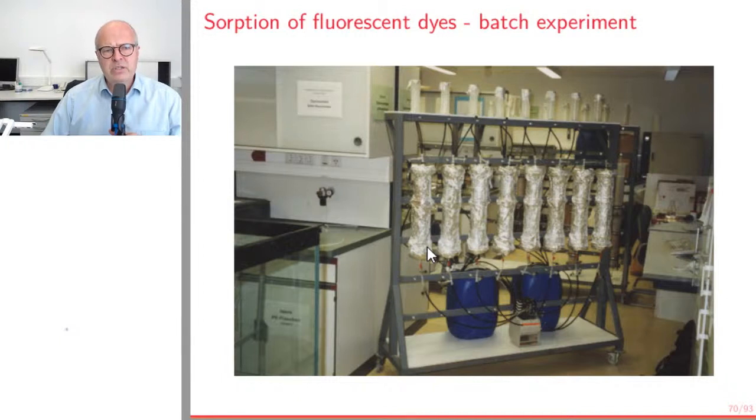If you do research and you want to work on the estimation of velocities and really try to avoid any bias, and you need to justify and thoroughly prove what you do, it's wise to do parallel column experiments in your laboratory and to double check whether the tracer works in that sediment and with the water type, for example, at a higher salinity, at a low pH, with high dissolved organic carbon in a polluted water, and so on. You should do these parallel experiments to validate your field experiment.